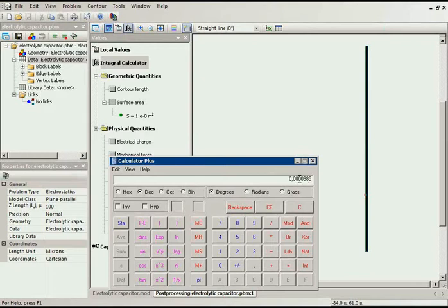It is 1, 2, 3, 88 microfarads per square meter. 88 microfarads per square meter of the anode foil. Now, if you know the foil area, you can calculate the capacitance of the real capacitor.